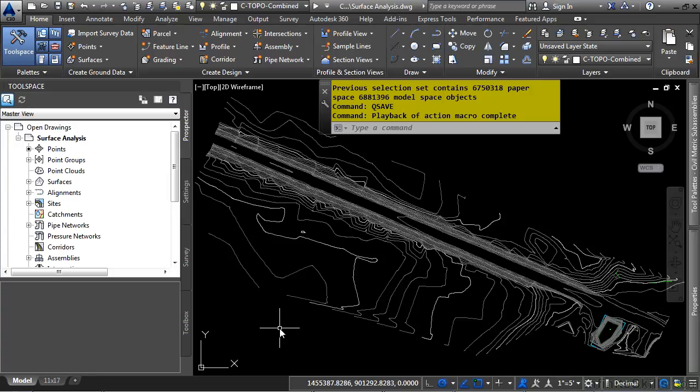Civil 3D has tools that allow you to see any kind of surface analysis that may be necessary during your design process. Some examples of surface analysis are elevation banding, slope arrow banding, and so on. Let's examine the workflow for displaying surface analyses. Let's first look at the settings and styles necessary to define.